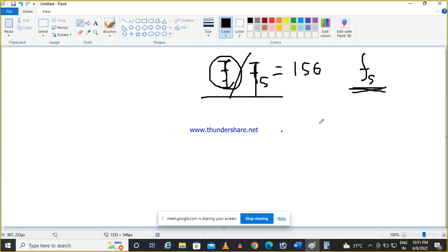Power frequency means our line frequency, it is 50 Hertz. Okay. So we are supplying this is the output that we want to get. Yes. So now my sine theta will be split into 156 steps. That means each step I need the value of, so first is 0, then I want the theta value. So here theta is equal to 360 divided by 156.